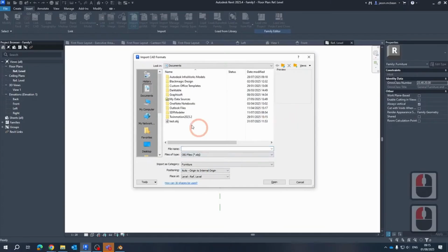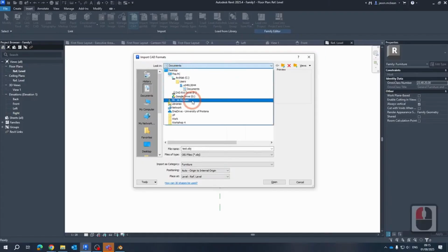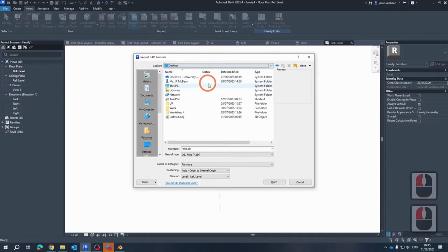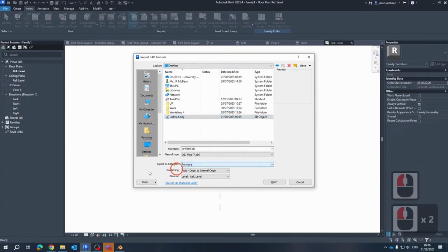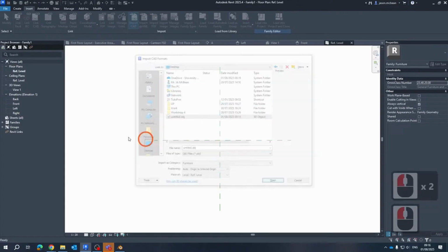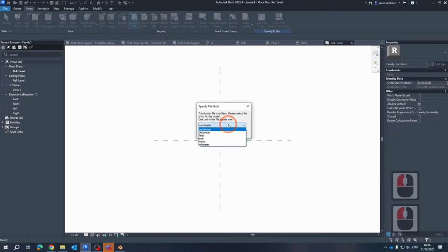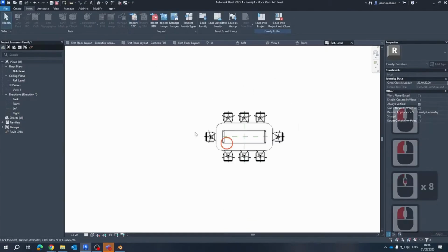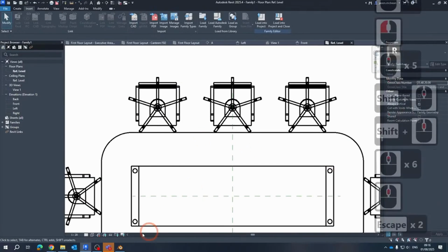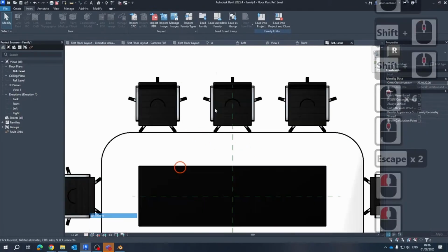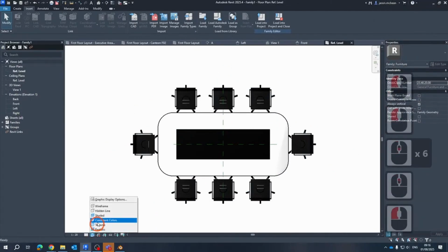Okay, OBJ files, in my opinion, work really well because they're not going to pollute your Revit file with unnecessary information. And you can see here, you can import this as the correct category. You're going to use everything as the same. You're going to simply import. Now this is the trick. Typically this is going to be meters, if it's coming from Blender. You will notice that the information, so if I shade this now,